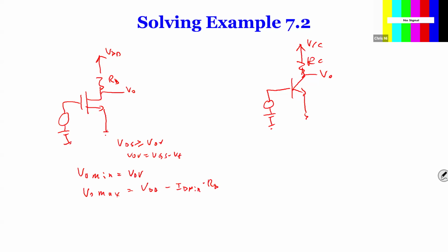Because you have to have a certain current to maintain this in saturation. If your current goes to zero, the whole thing is stopped, right? So you have to have a certain current. So in theory, you can get to the VDD, but in practice, there's a certain limit you cannot go above, right? So that's your output range for MOSFET.